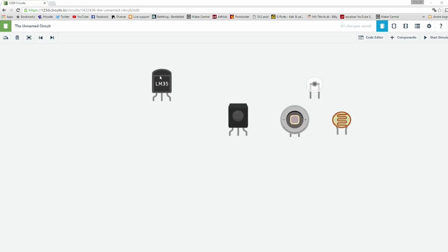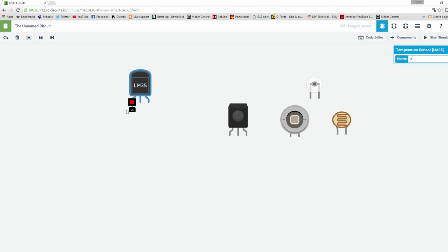It's going to send you a signal back, not a resistance, and the signal is going to be something you need to interpret to a temperature. The one I'm showing has three legs, meaning one of the legs has power in, one of the legs is ground or zero, and one of the legs is a signal. You can see it says V out right there.